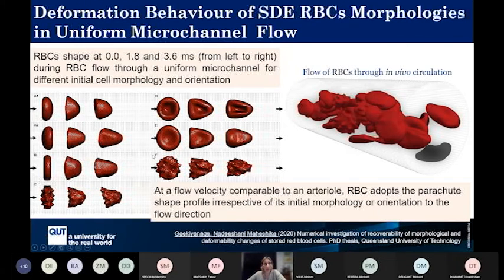What we are using at the moment is a coupled coarse grain SPH approach, because we had some previous students working on SPH, but again, the following step would be transferring or swapping the SPH for a Lattice Boltzmann, just because the SPH approach is very computationally intense. And so we hope that using Lattice Boltzmann, the efficiency of the simulation would be much faster.